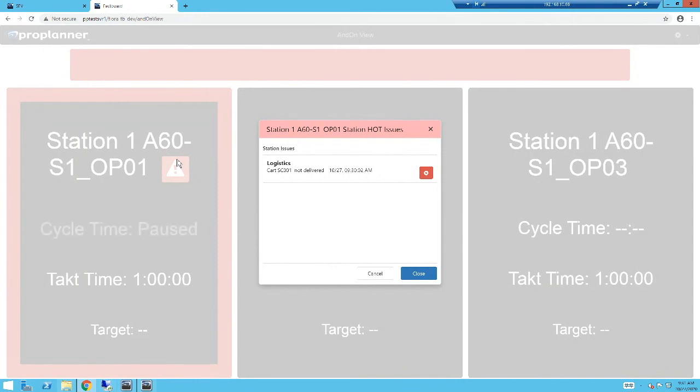And all of this information that you're seeing here is being collected at the back as downtime. Whenever an ANDON call is fired, it's being collected as downtime. You can report this information out so you can see per unit, per day, how many such calls were made, how long did it hold up the line, and what were the root causes. The more details you add in here about what's going on, the more details you can provide in your ANDON reporting, and you can get to the root cause of why your lines are failing.